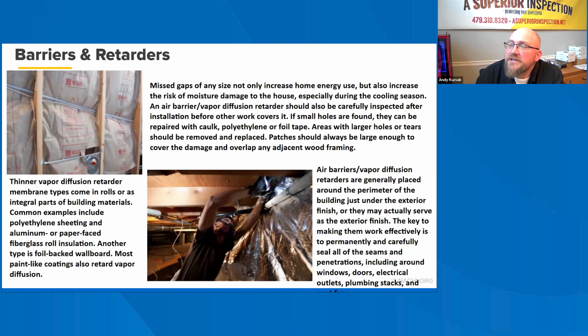Vapor diffusion retarders are typically available as membranes or coatings. Membranes are generally thin, flexible materials, but also include thicker sheet materials, sometimes called structural vapor diffusion retarders. Materials such as rigid foam insulation, reinforced plastics, aluminum, and stainless steel are relatively resistant to water vapor diffusion. These types of vapor diffusion retarders are usually mechanically fastened and sealed at the joints.